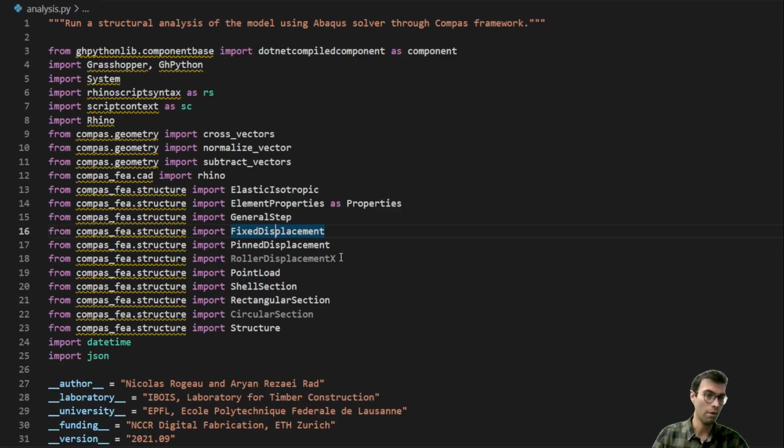Then, of course, defining again what I've already mentioned regarding the point loads, or defining the shell elements by identifying a shell section or rectangular section in that case to simulate the wood connections, the IMA, and then all of it will be translated into an input file to be introduced to either Abaqus, OpenSees, or other backends.